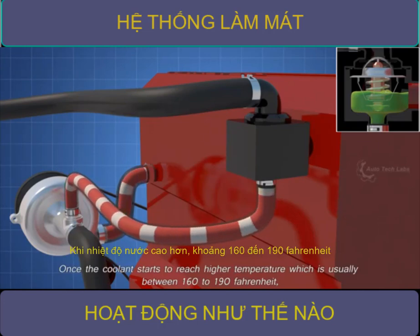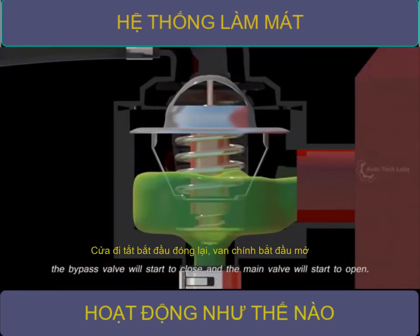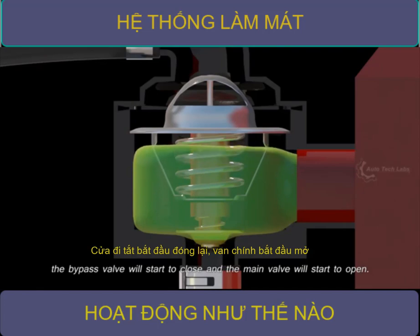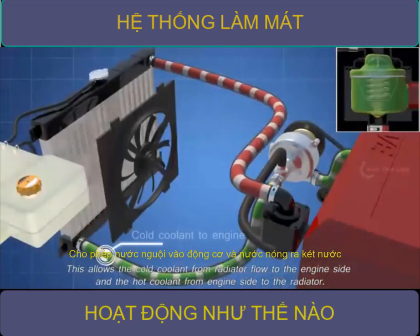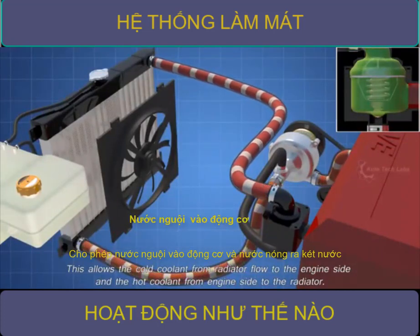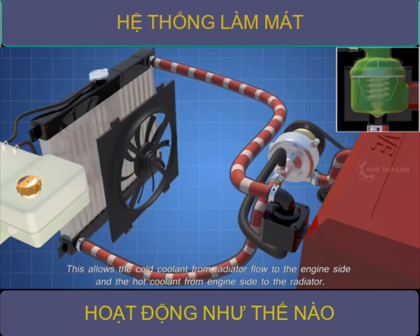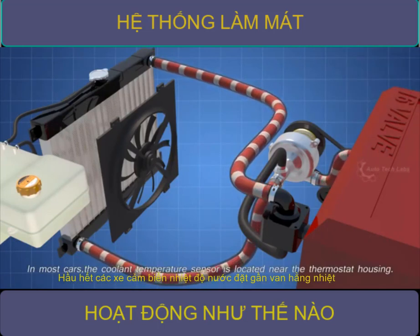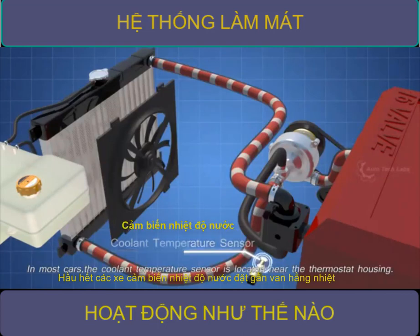Once the coolant starts to reach higher temperature, which is usually between 160 to 190 Fahrenheit, the bypass valve will start to close, and the main valve will start to open. This allows the cold coolant from the radiator to flow to the engine side, and the hot coolant from the engine side to flow to the radiator. In most cars, the coolant temperature sensor is located near the thermostat housing.